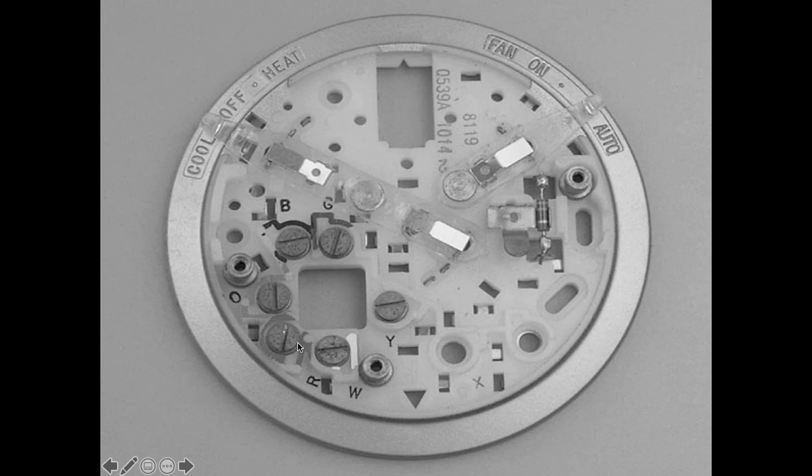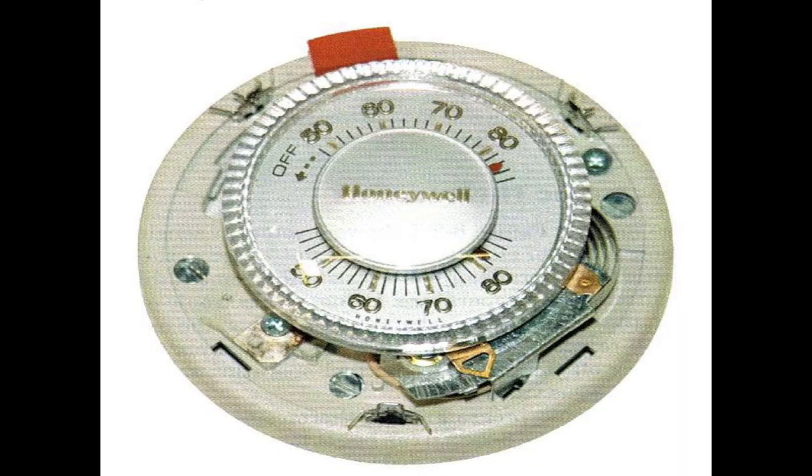They're labeled. We'll go into the purpose of all these later, but we have our system switch here. We have our fan on, and on all of these, there was a little pin where you could sit a level across them because leveling these was extremely important. And this is just a thermostat top. Now, again, you don't see these that often in the field anymore, but this little copper pointer down here was your heat anticipator setting, which was normally set to the amperage of your gas valve or the amperage of the relay that it controlled on the low voltage side.